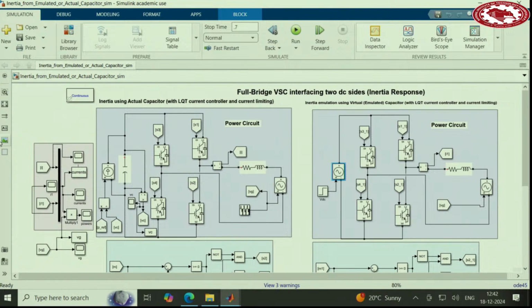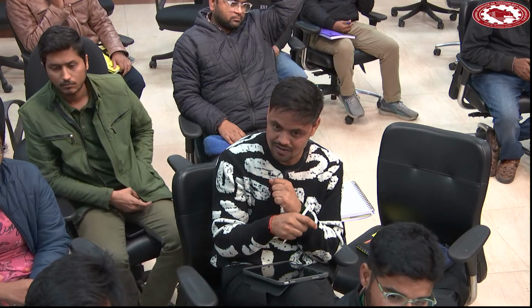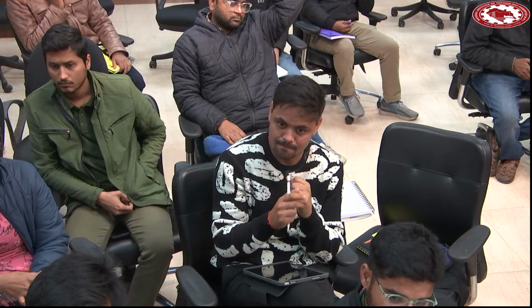Second, subsequently, if a DC link is there, with PV, DC link and then inverter, and the inverter is providing grid support. If the inertia I have chosen is very, very high, so the voltage is going down, it has to supply the energy. And if the DC link is not capable, the PV is not capable, what will happen? The DC link will break down at that time. Yes, if the voltage goes below the limit, the protection device will shut down the converter.